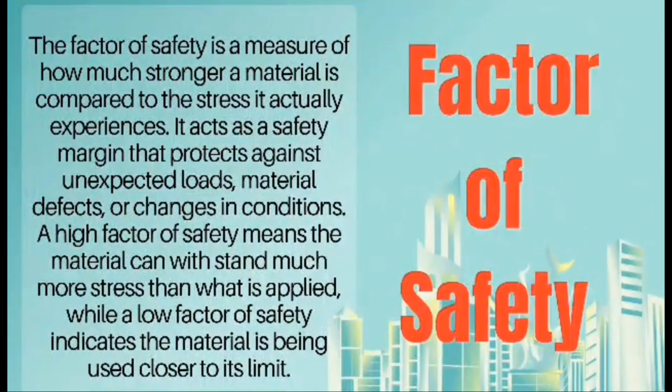Factor of safety. The factor of safety is a measure of how much stronger a material is compared to the stress it actually experiences. It acts as a safety margin that protects against unexpected loads, material defects, or changes in conditions. A high factor of safety means the material can withstand much more stress than what is applied, while a low factor of safety indicates the material is being used closer to its limit.